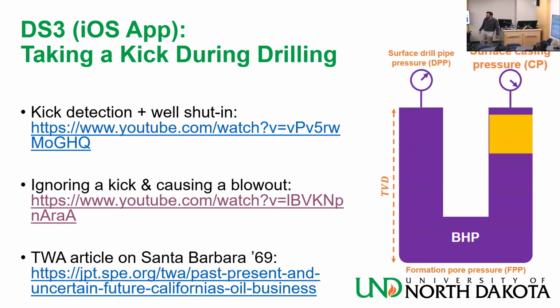It also increases, because it makes up what you are missing for the BHP to be equal to FPP. So it's going to be increasing, and there is a point where that value, say the casing shoe is here. This is your casing shoe. That value corresponds to the pressure here being equal to the fracture pressure. This is what you calculated in homework too.